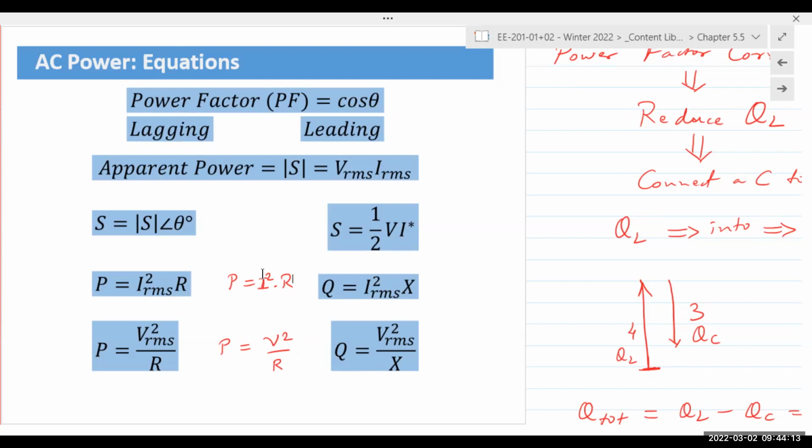All right. Also, capacitor, we said capacitor is negative, right? In real life, power is never positive or negative. We simply say the system has 500 watts of power or 500 VAR or 1000 VAR. It's never plus or minus. Plus or minus is to indicate whether the energy is flowing in or out and the phase difference, right? And so QL would be plus, QC would be minus, just for us to balance out the equations.